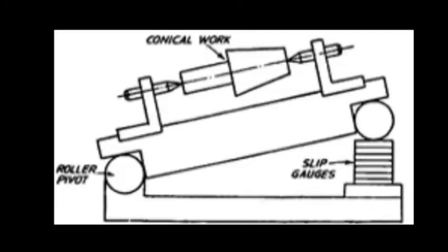Now, the sine table. The sine table is the most convenient and accurate design for heavy workpieces. The equipment consists of a self-contained sine bar hinged at one roller and mounted on its datum surface. The table is quite rigid, and the weight of the unit and workpiece is given fuller and safer support. The table may be safely swung to any angle from 0 to 90 degrees by pivoting it about its hinged end.